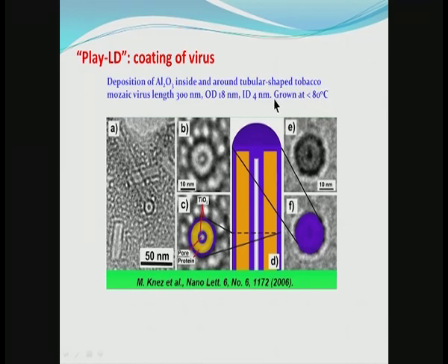As I said, trimethyl aluminum is a very reactive precursor, and when used in combination with water, or sometimes with ozone, it is possible to get reactions that produce Al2O3 at temperatures as low as 80 degrees. Such a low temperature is important because we are dealing with a biological material which is unstable at the high temperatures typically needed in ALD.